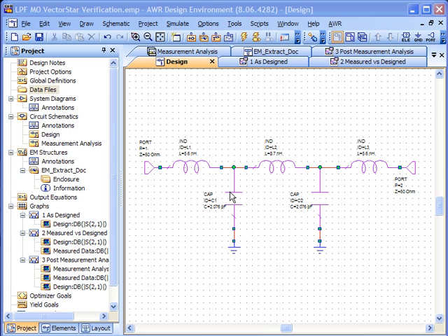In this demonstration, we're going to look at how the combination of Anritsu's VectorStar VNA and Microwave Office can be used together on the VectorStar platform. VectorStar is a brand new VNA from Anritsu that combines incredibly broadband performance capability with a fast measurement as well as a very high dynamic range, 100 dB approximately, which is very exciting for those of us in EDA because there's a very, very high dynamic range in simulation.